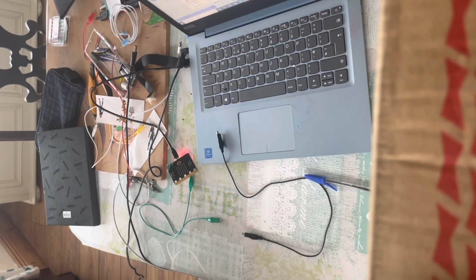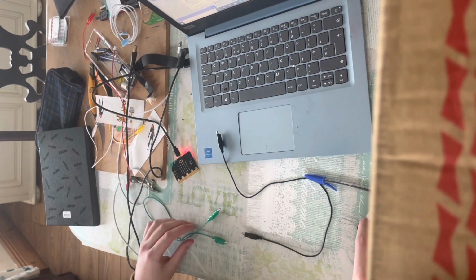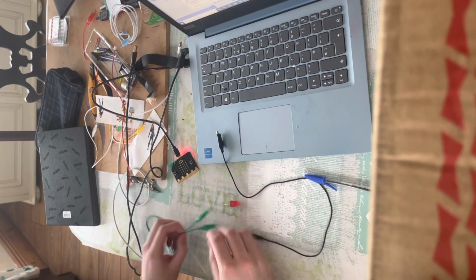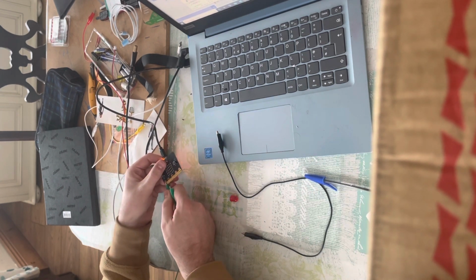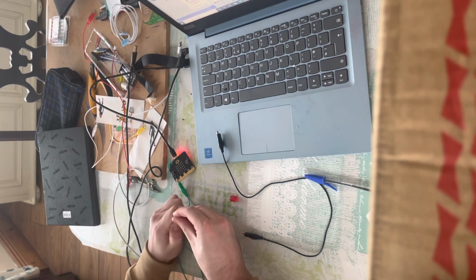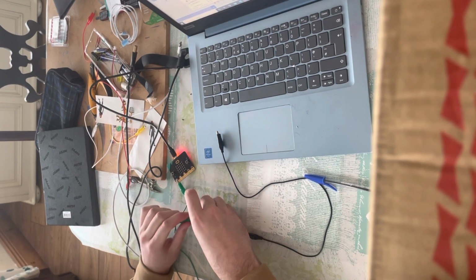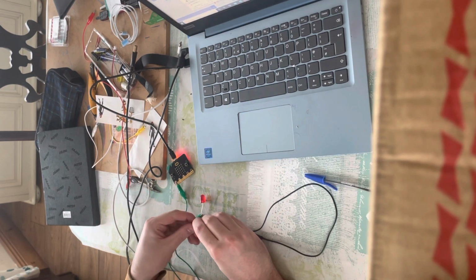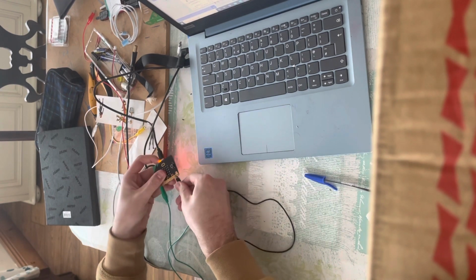Now, since we know how to actually code our microbit, we can transfer our code and download it onto our microbit from our computer. And then essentially we need to wire up our LED. So we know that we are using pin 0, so we put our wire to pin 0, we clip it on there, and then we set this wire from pin 0 to the positive leg or the longer leg of our LED. And then from the negative leg, or the shorter leg of our LED, we clip that back to ground. And then here we can see that our LED is flashing.